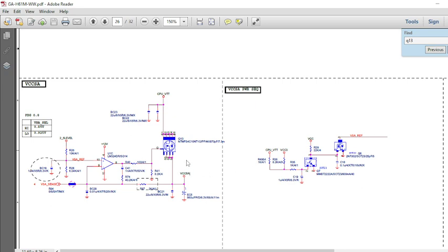Sometimes we receive an H61 motherboard with an issue where CPU VTT is there, but when we check, VCCSA will be missing, and when we check the VRM enable on our IC, the VRM enable signal will not be there. For that, this is the VCCSA power sequence section. You have to remove this MOSFET or this MOSFET. After removing these two MOSFETs, we will get our enable signal to VCore.